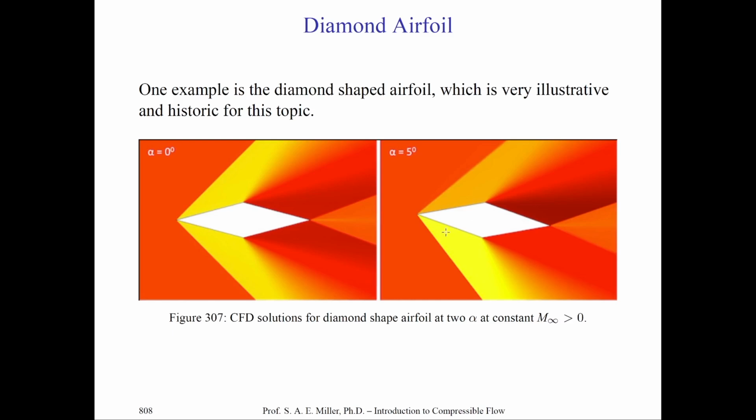On the left, it has a supersonic flow Mach number, which creates an attached oblique shock wave at the leading edge of the airfoil. And then the flow is turned around the airfoil and it expands and is turned back and reattaches to the airfoil through this expansion wave. So these are expansion waves above and below the airfoil. And the flow goes to a final oblique shock wave because, of course, the flow is turned once again to be parallel with the original direction in this particular case. Here, the angle of attack is 0 degrees, and indeed, you can see the flow is symmetric about the centerline axis or chord of the airfoil.